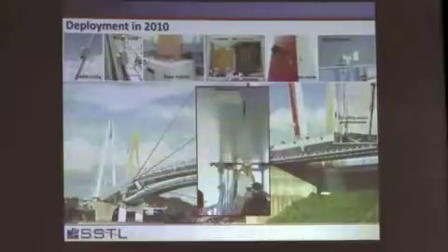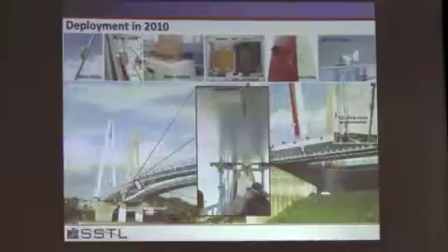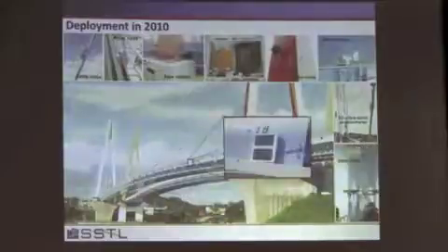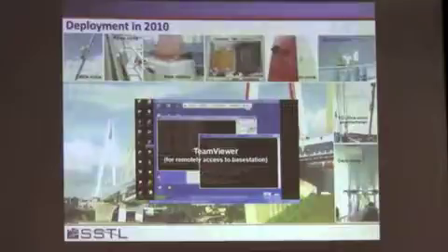And this was one of my students, Hongi Joe, and you can see the magnets attaching the wireless sensors to the bridge deck. So we didn't have to do any cleaning of the paint or glue or the like. They were held on strictly by the magnets. This was one of the solar panels that was on the side of the bridge. And this was the interface where we could access the data from any place in the world.